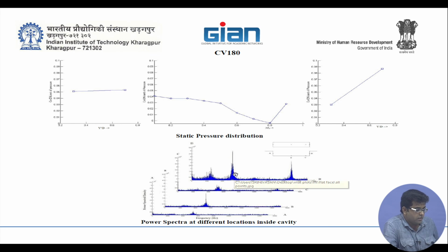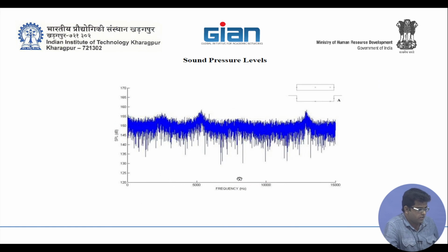So here the magnitude with say 5000 Hertz oscillation has very high magnitude. If we convert this to decibel, we can see mode 2 is reaching up to 160 decibel if we are looking at the sound pressure data. This is only for the rear phase. I am not showing the other phases.